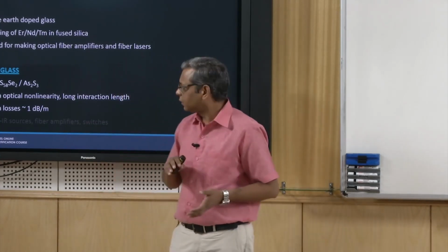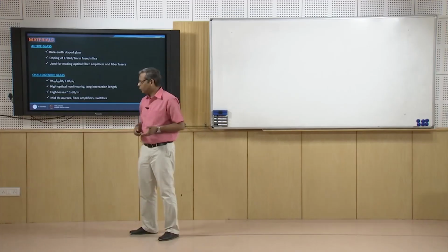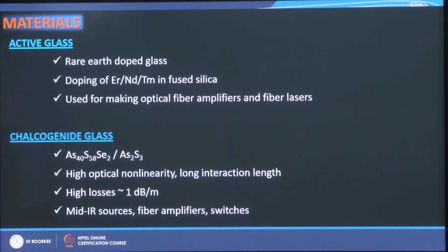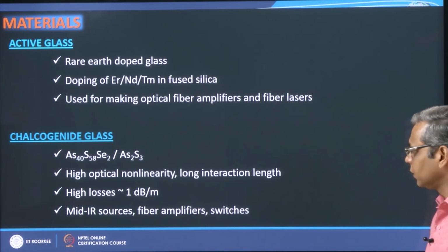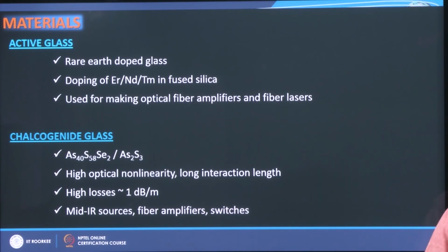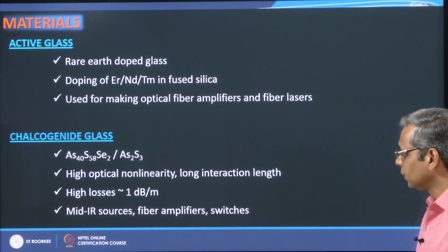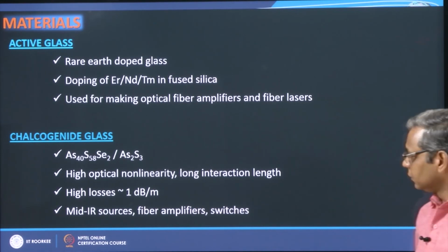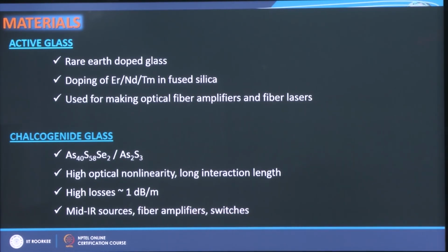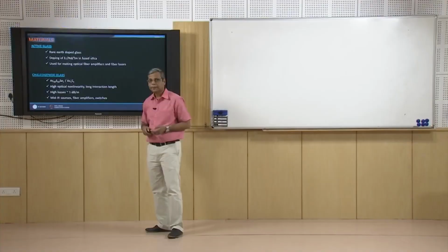In the fiber, the refractive index profile, geometry of the core and the cladding, and core concentricity are all decided by the preform itself. So preform fabrication is a very important stage, and the propagation characteristics of the final fiber are determined primarily by the quality of the preform. We should take utmost care while making the preform.